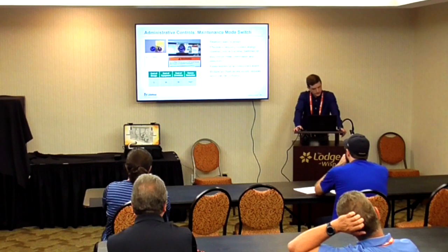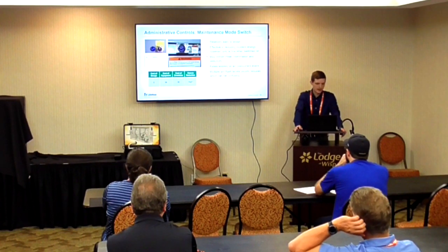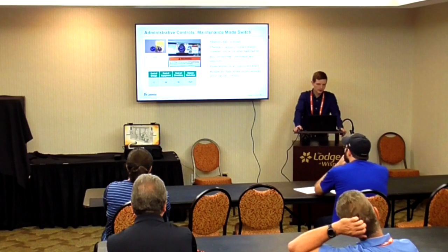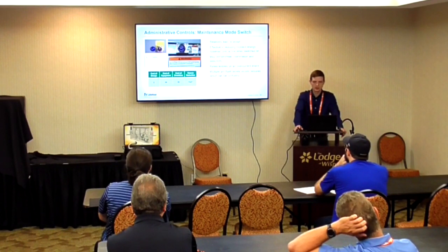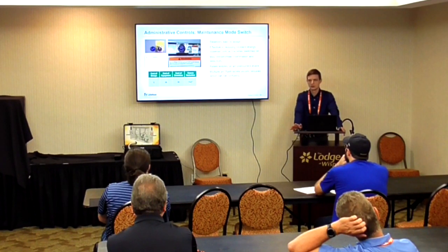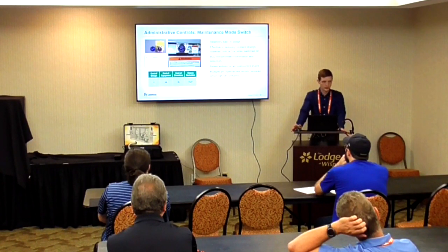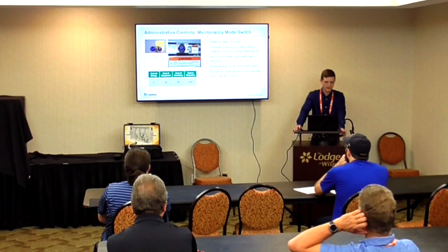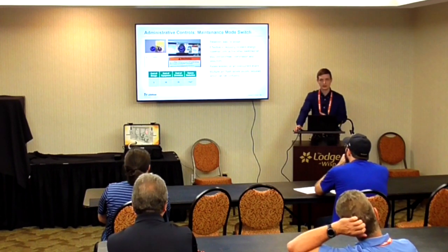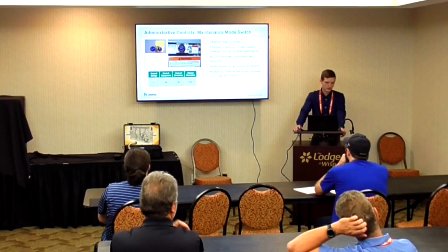The other thing that's a bit of a trade-off here is that the only time that you actually get this arc flash mitigation is when that switch is turned, meaning that even if the enclosure door is closed, so that you've got the moisture, so that 46% of faults that we looked at earlier, those environmental caused faults, or you've got a rodent or something that's in there, if that arc occurs and this is not arc resistant switchgear, you are still going to have that possibly damage the enclosure or damage everything else that's still inside there.